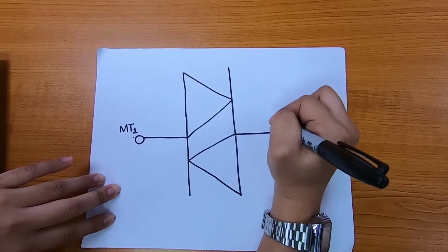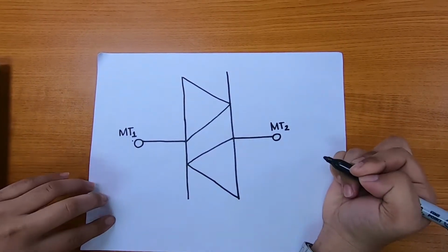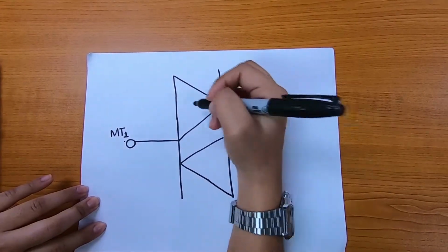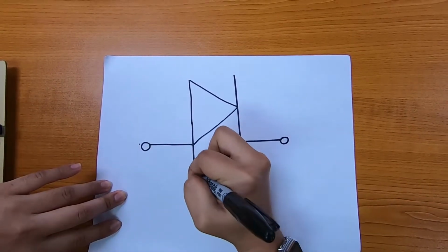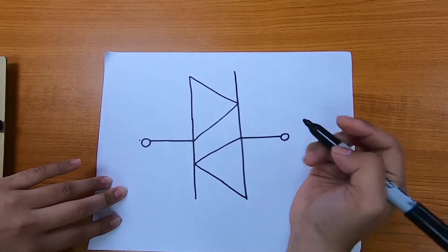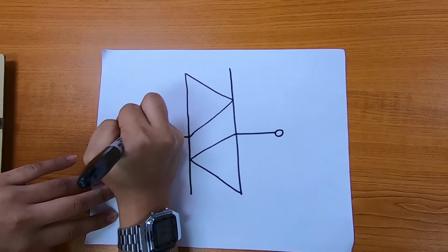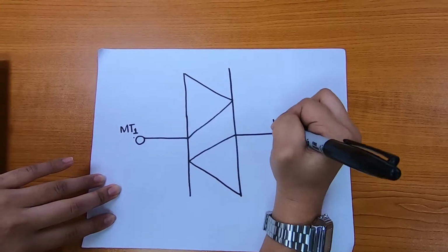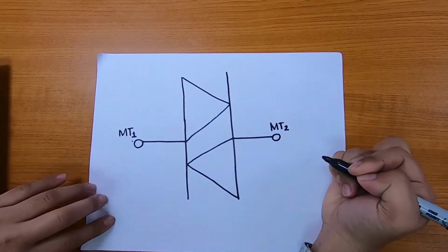Since the DIAC prevents any gate current flowing until the trigger voltage has reached a certain voltage in either direction, this makes the firing point of the TRIAC more even in both directions. In view of their usefulness, DIACs may often be built into the gate terminal of a TRIAC.